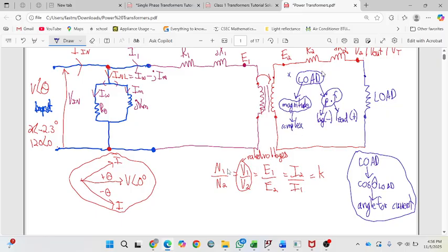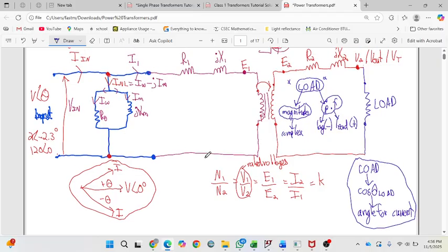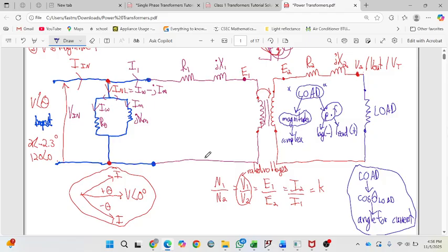So that is the load. Anytime they give you the load power factor, don't get confused. Take the load power factor and convert it to an angle. If it's lag, it will be the negative of the angle. And then you need to calculate your current magnitude, which is an entire story by itself, right? But just know, if they give you the load, you can calculate the power factor and the angle, and you can go straight back to the beginning. So let's just start over, do it one more time and jump straight into the tutorial.